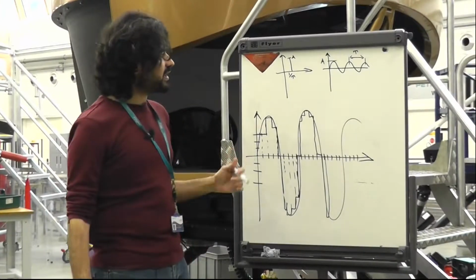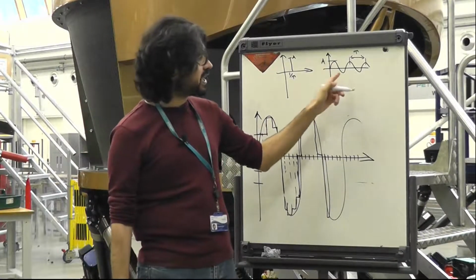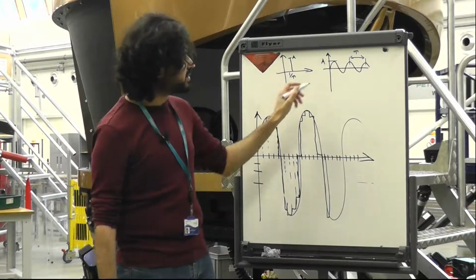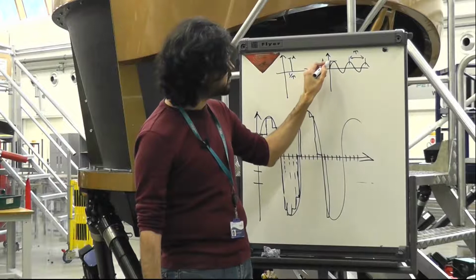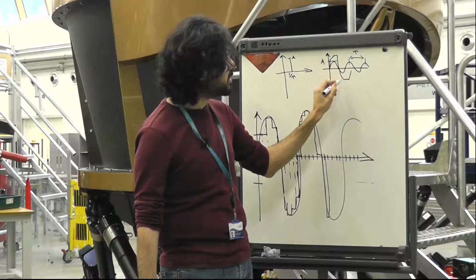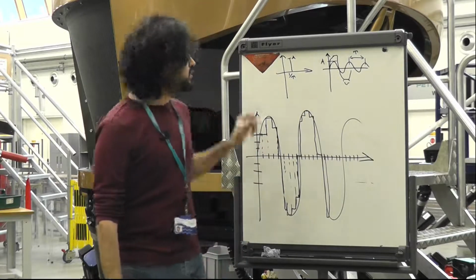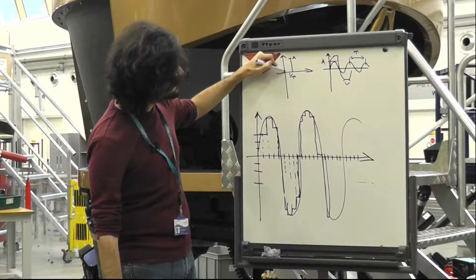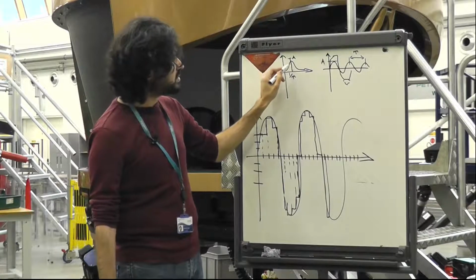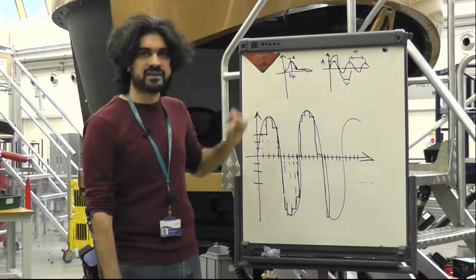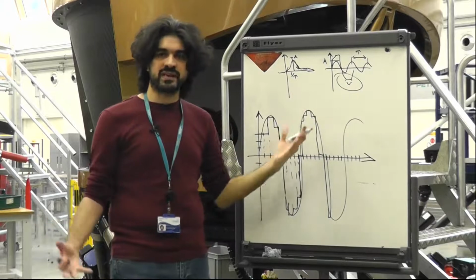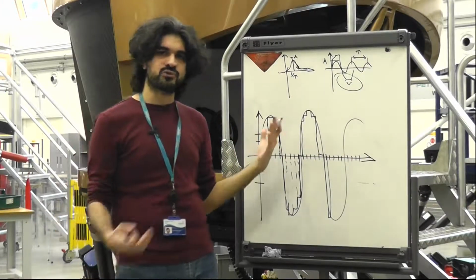Okay, so what I was saying is that the FFT of a sine wave looks like this, very sharp, but if you have an FFT of a clipped sine wave, so something that goes out of bounds, you'll see something like this. So this has a very large error over every other frequency, so this out of range, this overloading of the channel, you want to avoid.